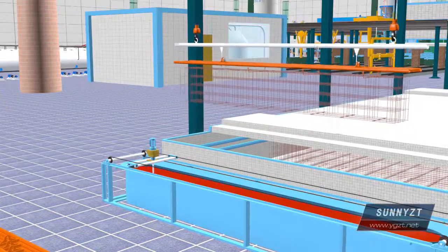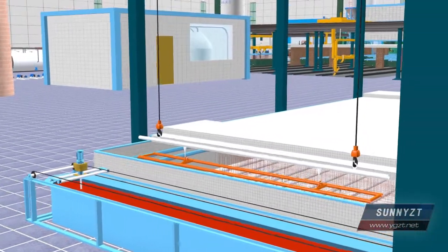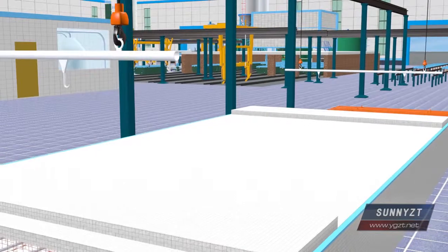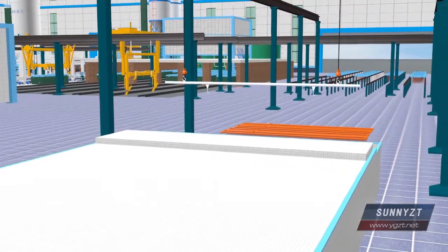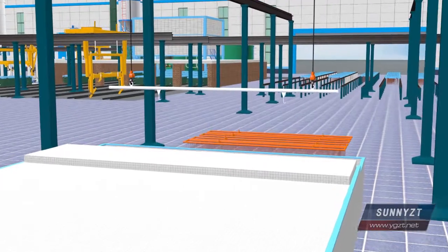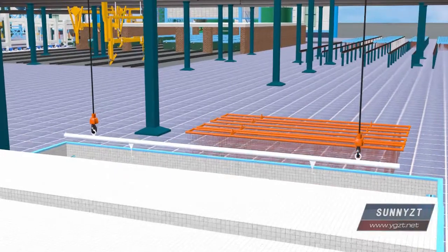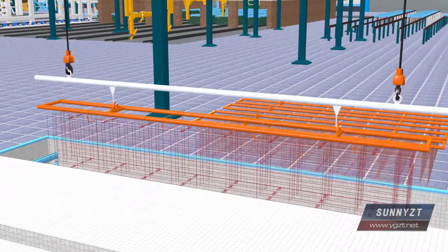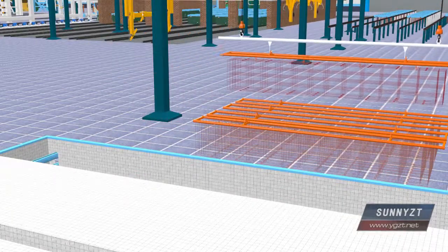After the penetration, hoist the mesh cage inside the mesh cage drying machine to do drying for 8 to 10 minutes. After that, hoist the mesh cage to the mesh cage installation region for installation before inserting of drill rod.